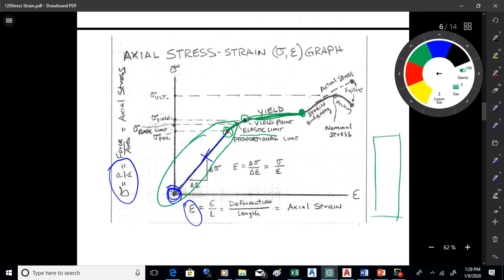It's not a perfect crystal like a diamond or a ruby or something like that, but it's still in a crystalline structure, but it has these lines, these fault lines running through it of imperfections. What happens here when you really start to yield the material is all these fault lines start sliding together and they run into each other. And that hardens the material up a second time, and that's called strain hardening.